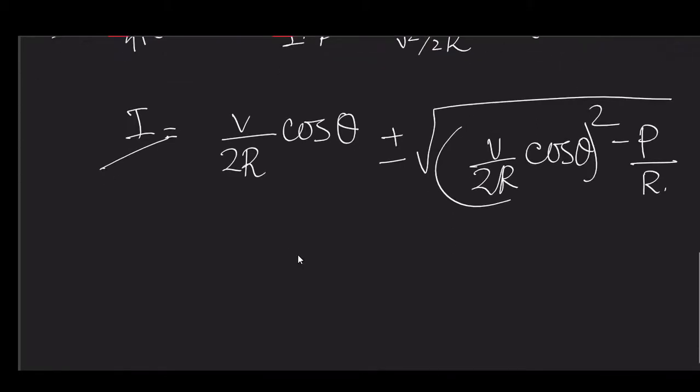Well, now let us see what would happen when we consider it as a function of our armature current, as a function of excitation. So, for the armature current, we can write V, our terminal voltage, is equal to E plus IZs. If you follow Langsdorff, what Langsdorff did, following the same notion as for the transformer, where we used to represent